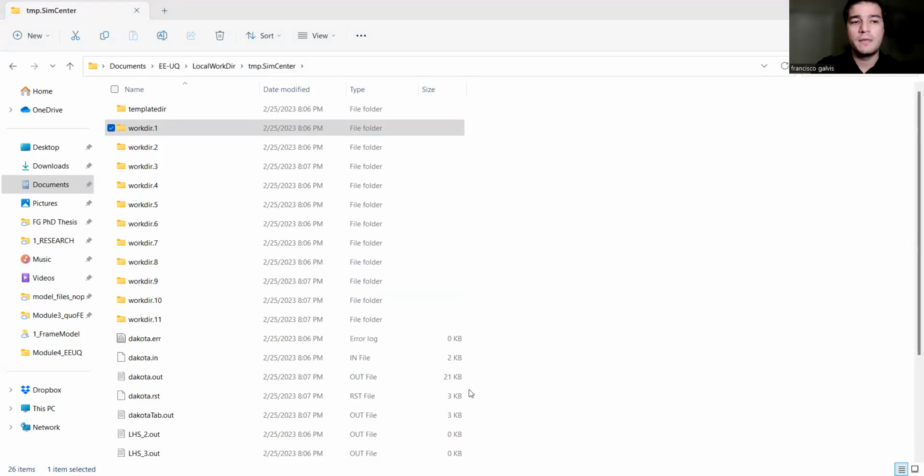All right, so this is the result. So basically for each of the stories, you get peak floor acceleration and peak floor displacement, and also a peak interstory drift. You get a mean and standard deviation from those 11 numbers, right? You can take the data values and export them as a table. So you can say save table and save that.